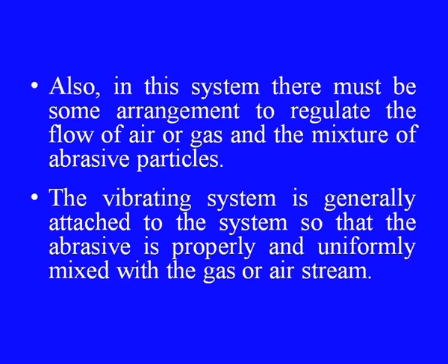Also, in this system, there must be some arrangement to regulate the flow of air or gas and the mixture of abrasive particles. The vibrating system is generally attached to the system, so that the abrasive is properly and uniformly mixed with the gas or air stream.